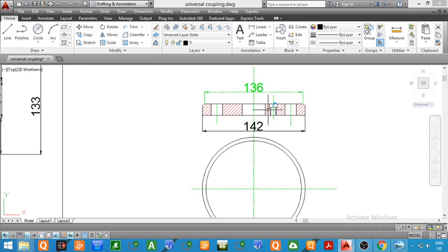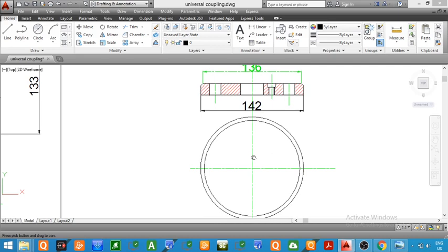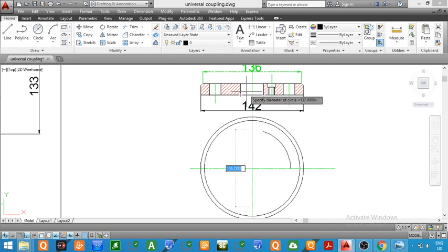Now we have to draw this center hole. This hole, if observed from the top view, will be what? Circular, because it is cylindrical in nature. So the top view of this cylindrical hole will be a circle. For drawing this circle, we know the dimension. The diameter of this hole was equal to 64. In the question it was given 64, but we have taken half of 64, that is 32. So now here we will draw a circle of diameter 32 mm. So this is the top view of the cylindrical hole which is present in the center.